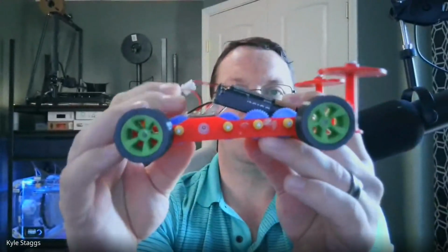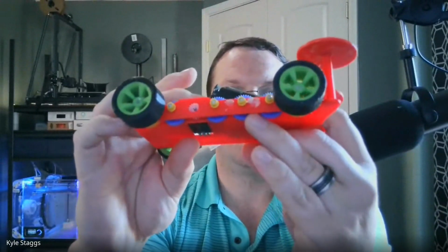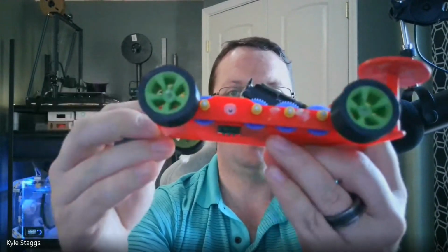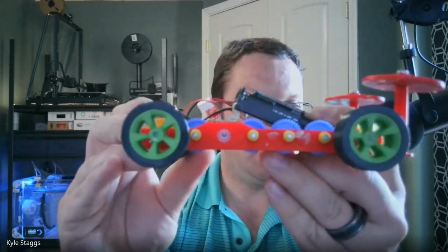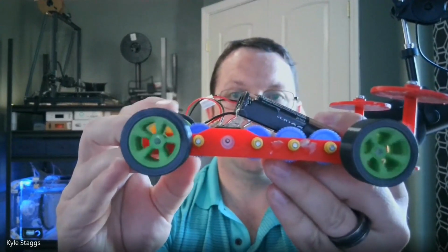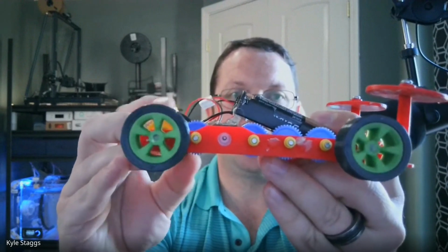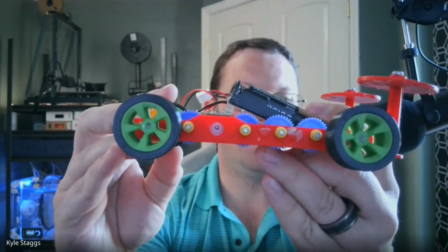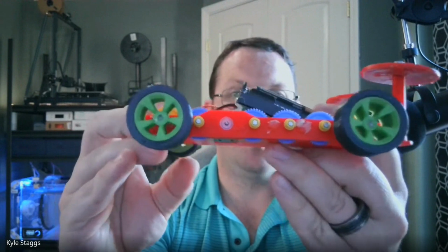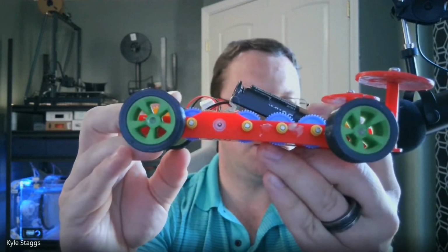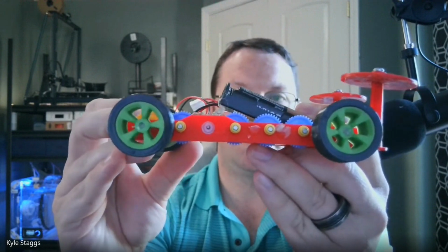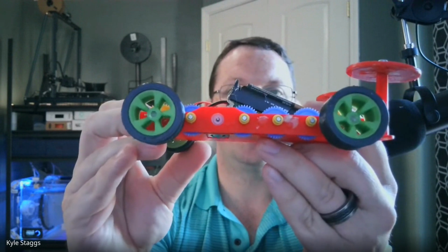The problem with that is these motors have virtually no torque whatsoever, so they don't have enough torque to overcome the basic rolling friction to keep them moving. But you can see when I turn one tire, all four rotate at the same speed exactly. So that keeps things very, very easy. There is a little bit of gear lash, which means if I hold the tire steady, it wants to move. And the more gears that you have, the more gear lash there is to take into account. So there's a little bit of play and rotation there. In this case, it's across all of those gears, almost an eighth of a turn.